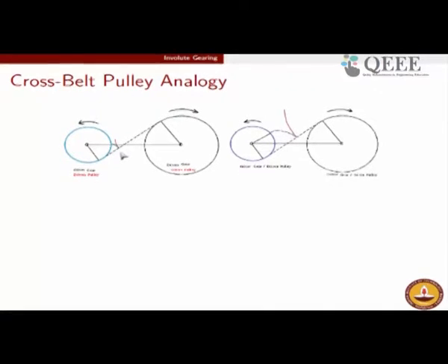Please note, during this entire course of motion, the common normal between these two profiles is nothing but the cross belt itself, right. The cross belt is the common normal. The point of contact always is basically that pencil. The point of contact associated with these two profiles is basically the pencil which you had attached and which is generating these two curves.